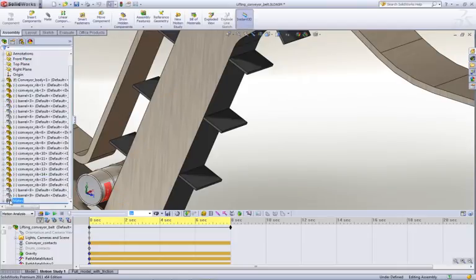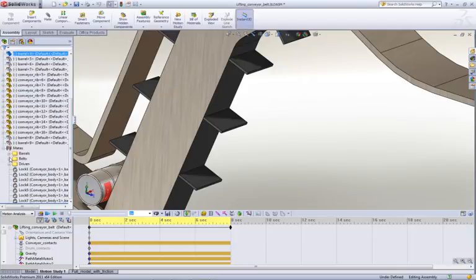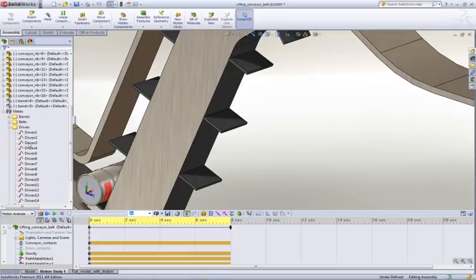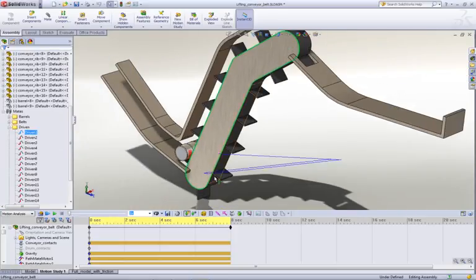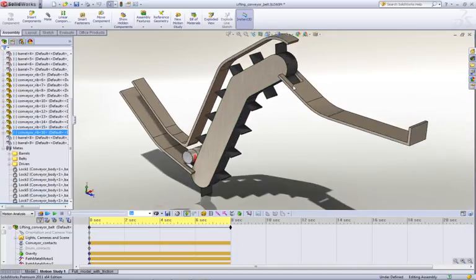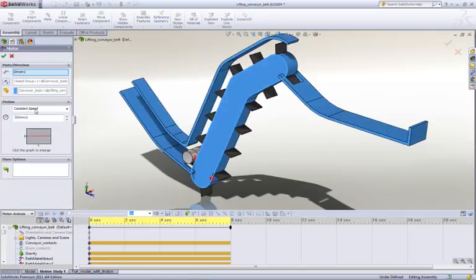In Solidworks, you can define pathmates, which are basically points which have to follow an arbitrary profile. So for example, in this instance, the point here is free to travel around the conveyor path. So it's a very powerful tool for doing things like overhead cranes, conveyors, roller coasters, all those types of things. You can now drive things along those paths with specified speeds or whatever function you need.